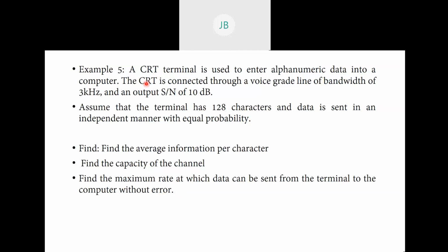First we need to find out what details are given in the question. One is the signal to noise ratio, which is given in dB. Generally, signal to noise ratio is a number because there is no unit associated with it. It's a normalized value. For example, signal is a power, noise is also power, so when you find the ratio, it becomes unitless.